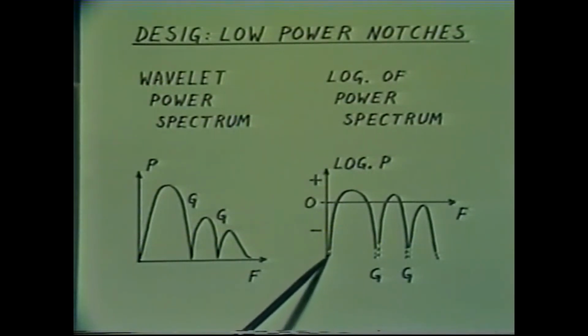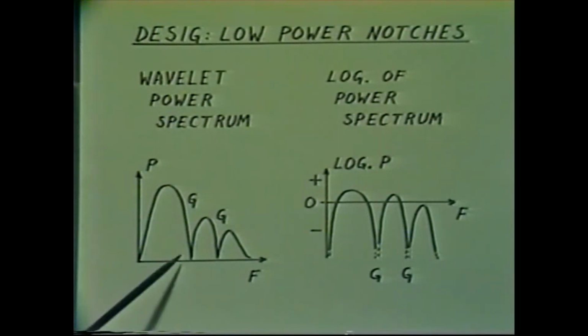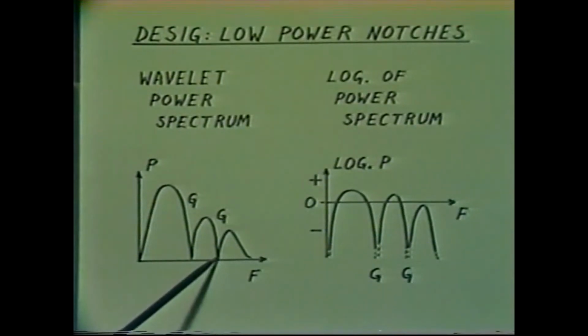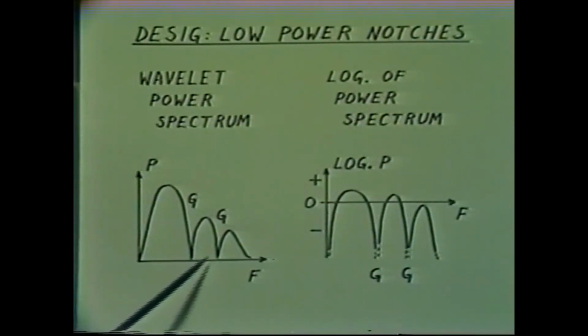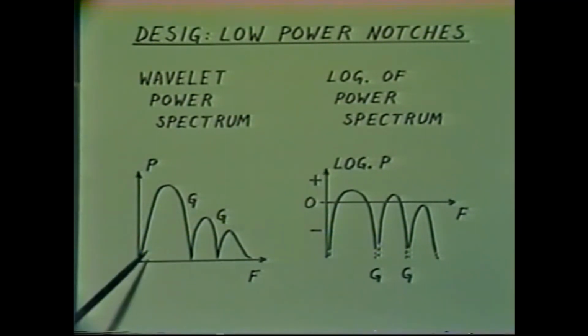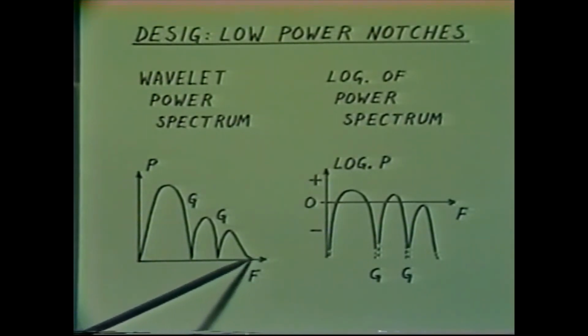Now, it is these numbers of highest magnitude which mainly control the phase spectrum that is computed by means of the Hilbert transform. Therefore, in effect, it is the low power points or low amplitude points on the spectrum which determine the minimum phase spectrum that is computed. It's therefore very important to measure both the frequency and amplitude of these low power points on the spectrum accurately. And that is the reason why the amount of white noise that is added to this spectrum before the computation is extremely small.